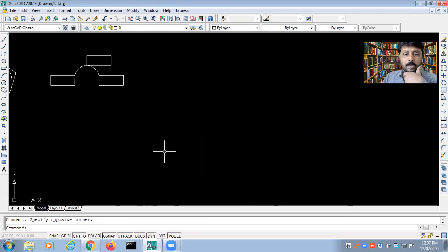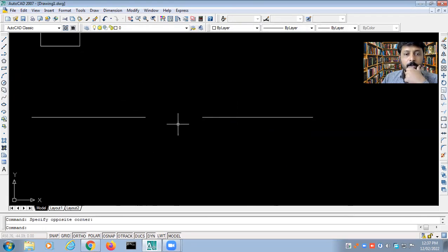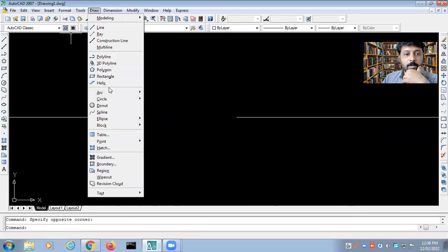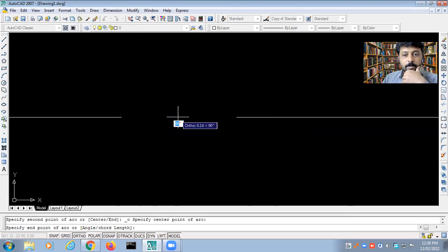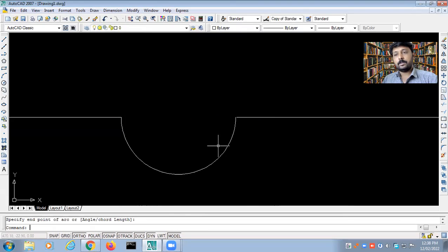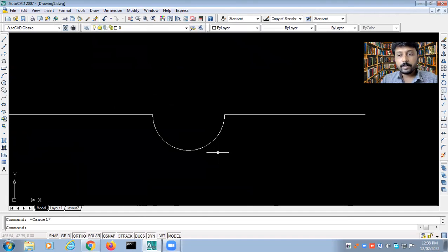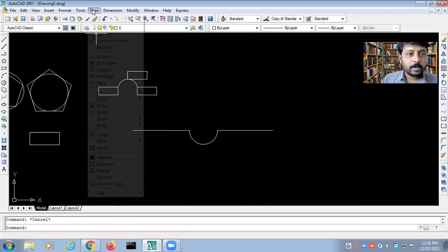Okay, I want to draw the arc over here. I know the center point. Okay, suppose I know the center point. So I will go to arc, start, center, end. This is how I can create an arc. Okay, so this is another type of arc.